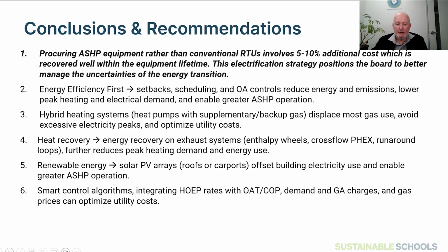Don't forget to make the schools energy efficient first. So look at the schools that are planned for rooftop unit replacement in the coming years, and prioritize them with your energy efficiency work. Hybrid, we recommend. Look at heat recovery and make sure you apply it wherever you can. Look at renewable energy options, and talk to your consultants and equipment suppliers around smart control algorithms.